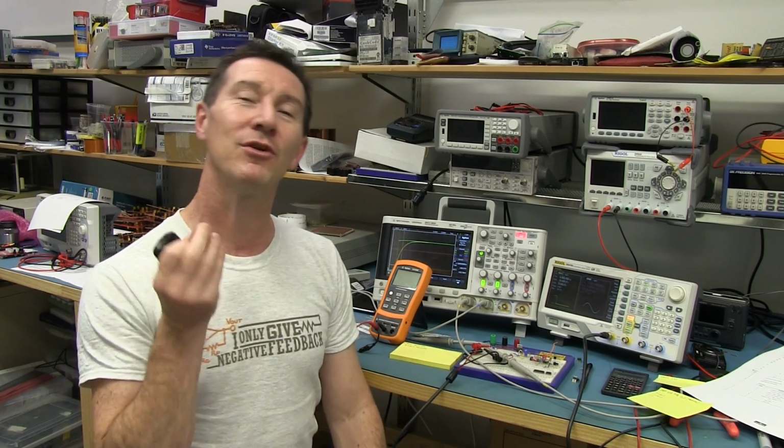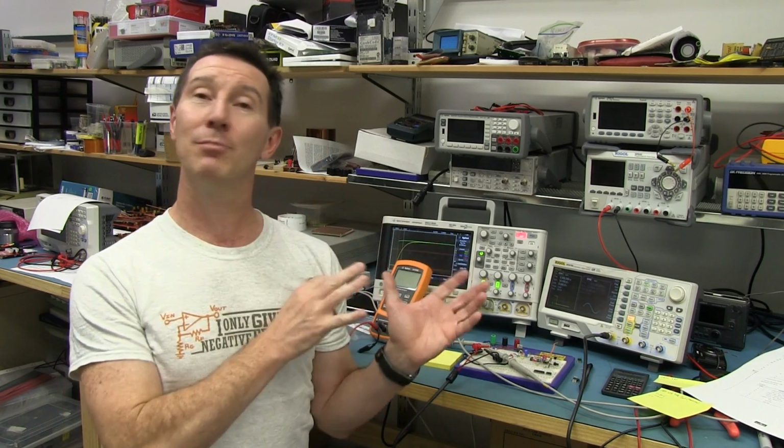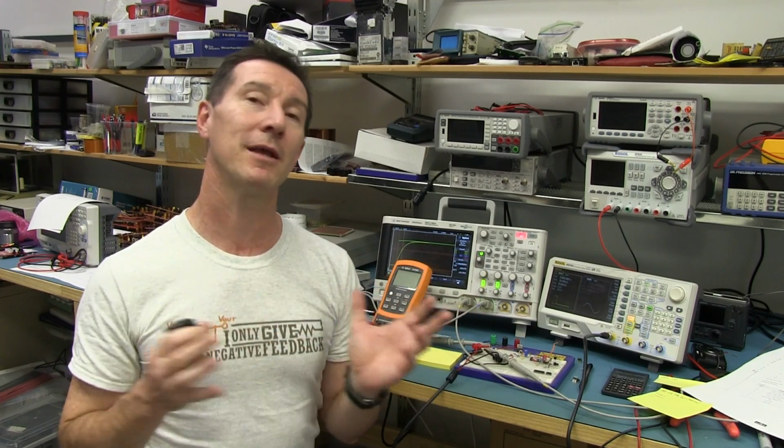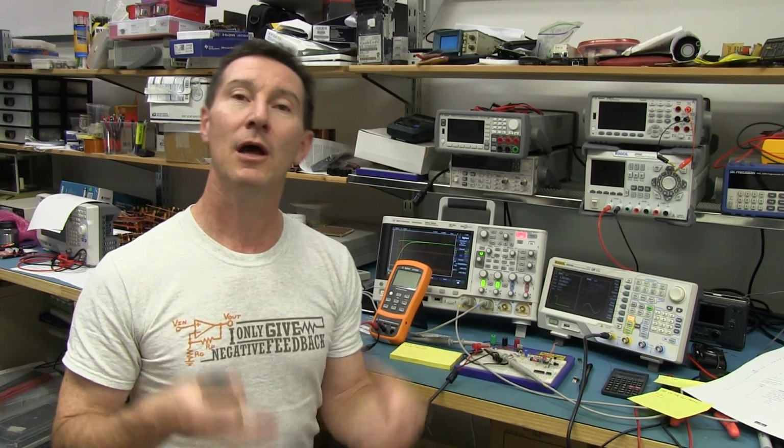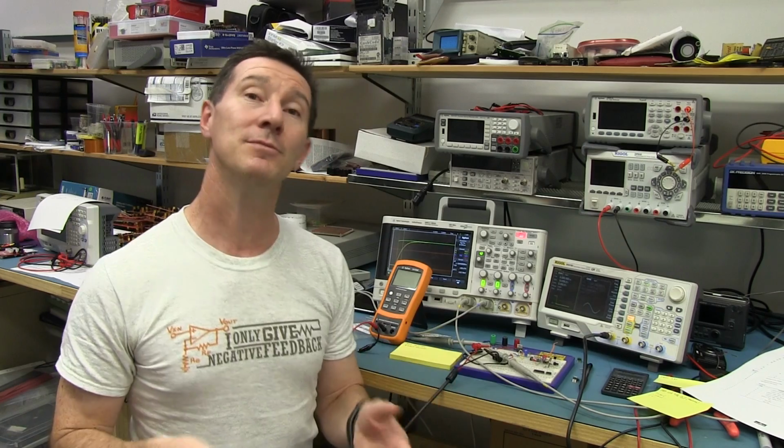They're fantastic, with all this wonderful materials technology that goes in them to give you incredibly high capacitance in incredibly small volumes for SMD and stuff like that. But yeah, there's a few downsides, and it's not just temperature, it's voltage as well. A trap for young and old players alike, certainly. Now, this only applies to class 2 and above ceramic capacitors. It does not apply to electrolytic capacitors, tantalums, and class 1 NPOs and things like that.